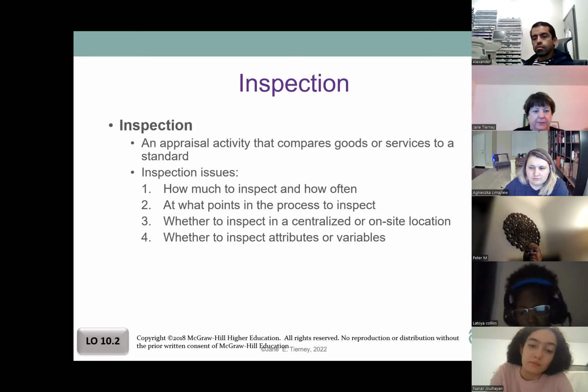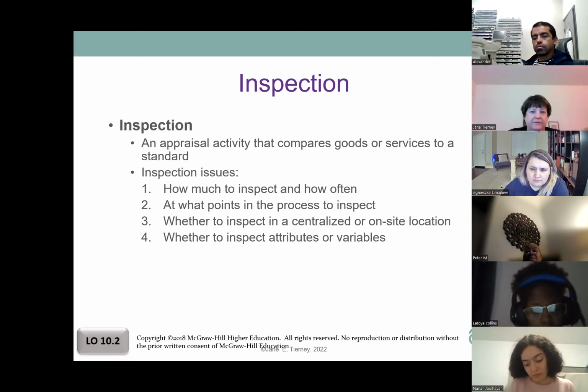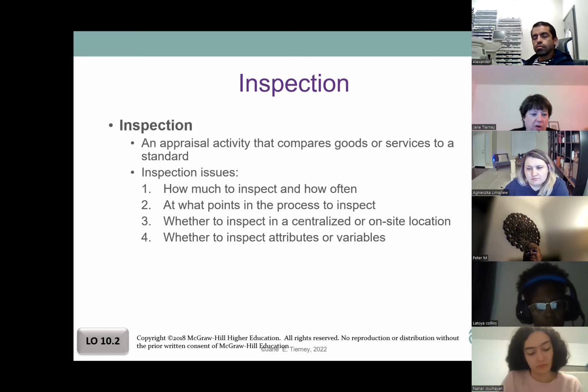If you, for example, have concrete countertops in your home, those are typically really smooth. They're not rough, right? But some applications of a foundation can be left a little rough. If it's a garage and it's going to be exposed, you want it to be pretty smooth. So you have to say, what's my specification? And then what does this look like in regards to that? So we can check all of that.